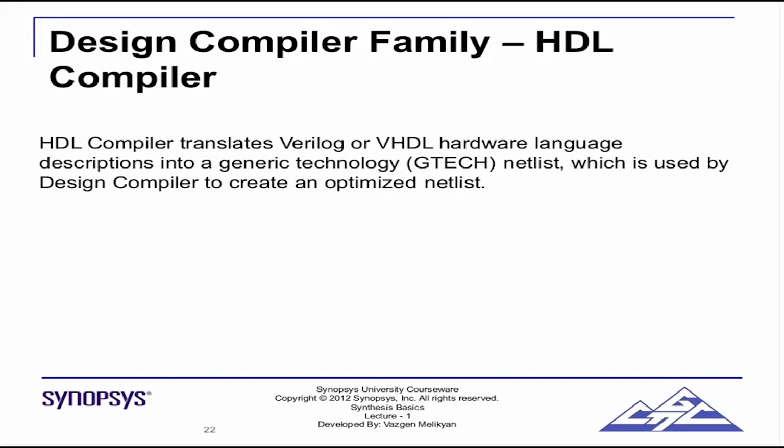Not 100% of Verilog is synthesizable. There are constructs which do not have any hardware equivalent. For example, in Verilog, many times we want to delay something, we write hash and a number. Let's say #5 A = B. That is, B is being assigned to A after 5 units of delay.